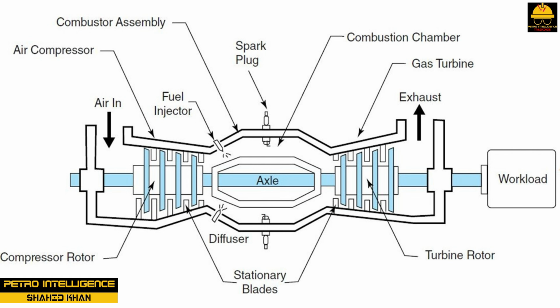Axial flow compressors have replaced most other compressor designs because of the large volume they can handle. The combustion chamber combines two feed components to produce a continuous, high-pressure flow into the turbine. The gas turbine has a number of stages that increase in size to accommodate the expanding hot gases that jet through the moving turbine wheels and stationary blades.